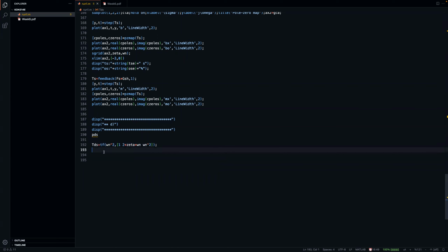Now, the question is actually the following. Instead of using a fixed structure controller with the system in a feedback loop to end up in the best dominant setup as possible, what is the controller structure or the exact controller that gives us this ideal transfer function? So now we don't know what the controller looks like, but we know what the closed loop looks like. And we know what the system is. So therefore, we are going to work out what the controller should be.